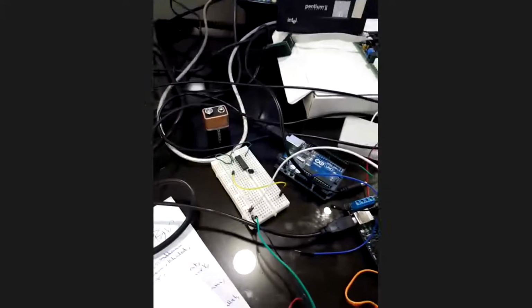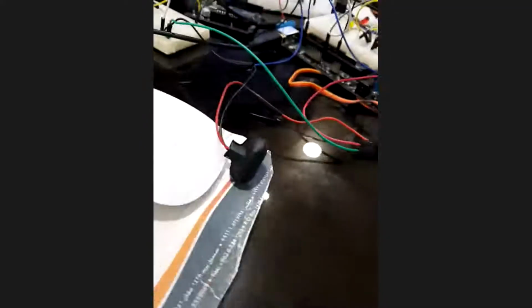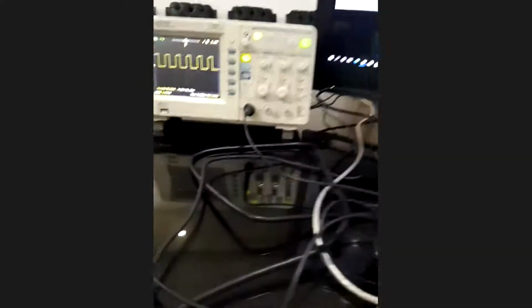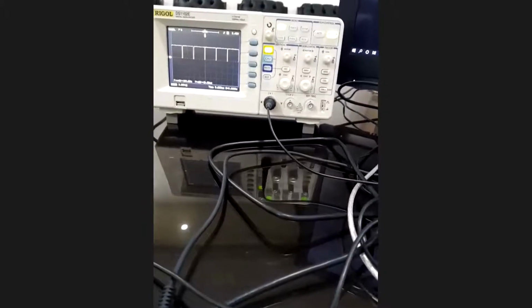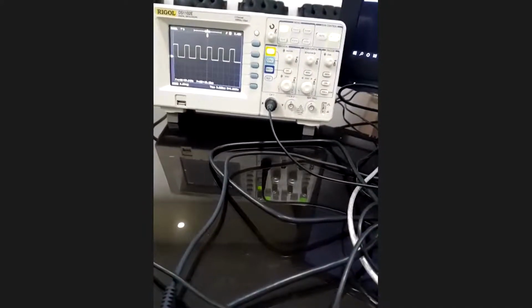We did this in the past. You can take this pulse width and connect it to your motor through an NMOS transistor by sending this port P0 to the gate of the transistor. The motor will start turning on and off real quick, and you will be controlling its speed. We did the exact same example with the Arduino, if you remember. But now see, we're generating a PWM signal as easy as that. This is an 8-bit example.